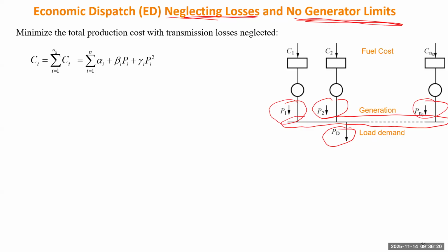And each cost of the power plant is formulated by a quadratic function. To calculate total cost, we simply add all the quadratic functions together. So that will be the total cost of this system. And there's just one equality constraint, where the left-hand side will be the total input, the right-hand side will be the total load. Okay, we are going to solve this problem.